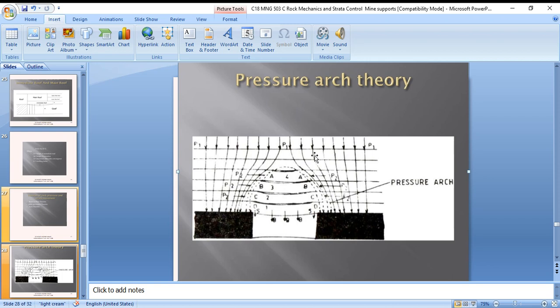As a result, there are five zones, numbered 1, 2, 3, 4, 5, as shown in the figure. Zone 1 and zone 2 are de-stressed areas, which are the stress relief areas. The lowest layer, zone 1, is thinner and weaker. It tends to sag more and separate.